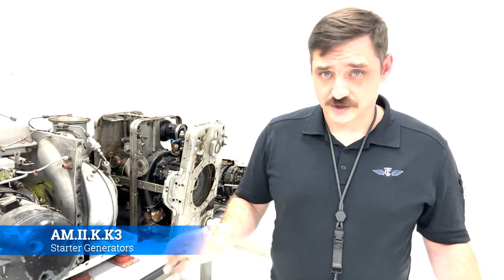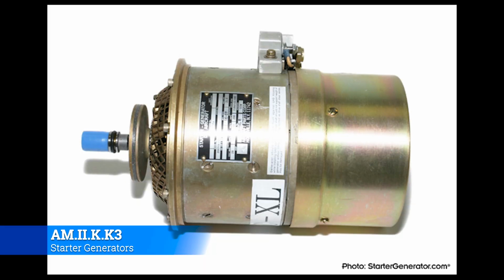Now, starter generators are pretty well ubiquitous across all turbine engines. Some of them don't have them. Some of them you might use something a little bit different. But I guarantee you, if you're going to be working especially in the business, corporate aviation world, starter generators are par for the course. I know for a fact if you end up working on a Bell 206 or 407, they have a starter generator that's about like so big, and you'll end up having to change the brushes and all the other good stuff.